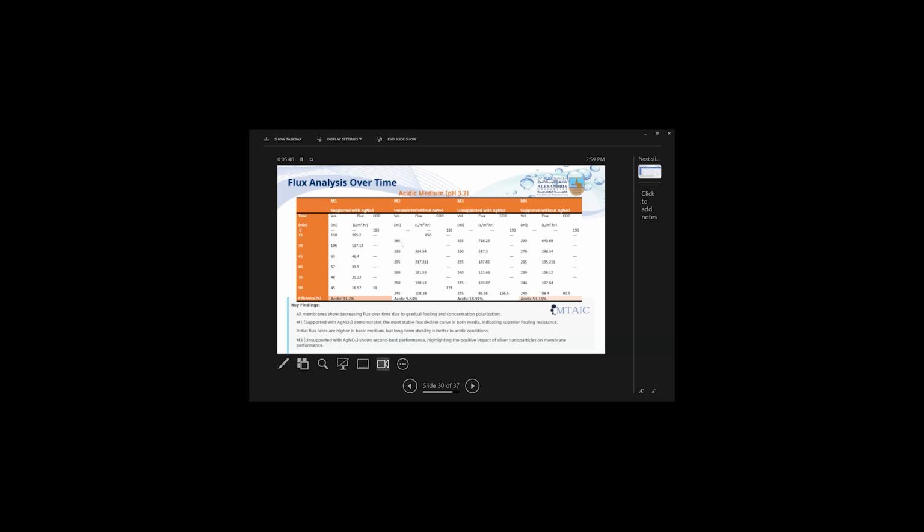As you can see here, we calculated the efficiency in relation to the chemical oxygen demand, COD. Why? Because the azithromycin contributes to the organic content of the wastewater. So in order to find a direct correlation between the COD and the azithromycin, we chose COD as the major measure, as it has a direct proportional relation to the azithromycin.